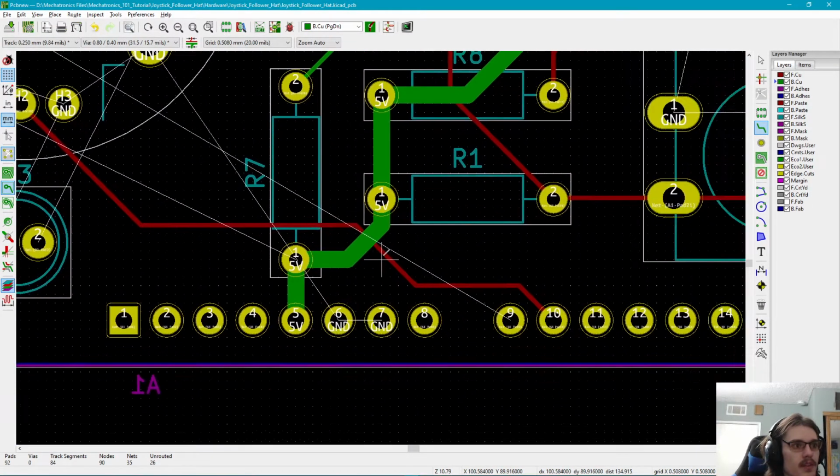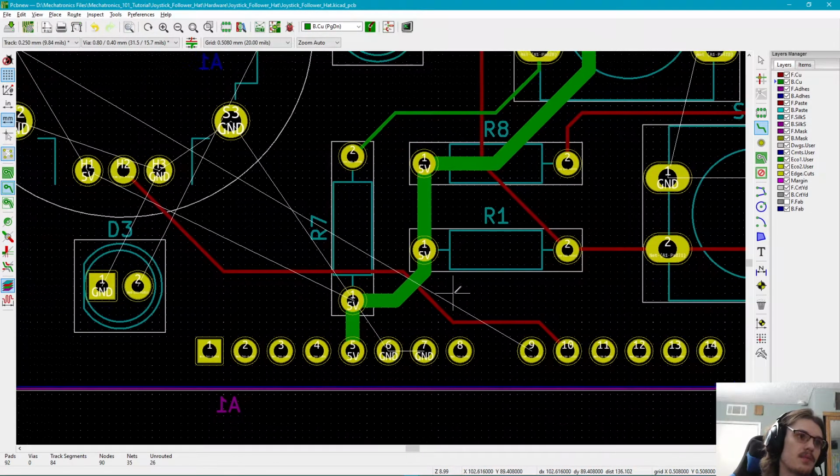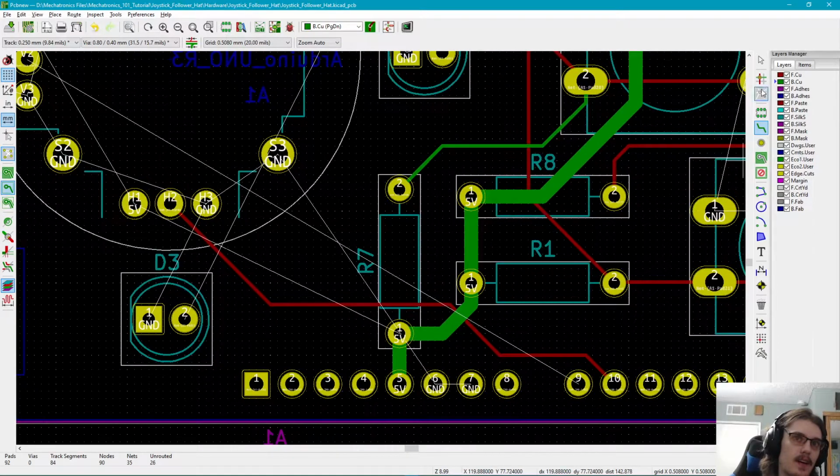So what we're going to do is use a small via to essentially go where it's green, we're going to go under it with a red trace, and then where it's red, we're going to go under it with a green trace. But when it's green, we're going to go back over it on the red trace. We'll be switching back and forth between the planes.